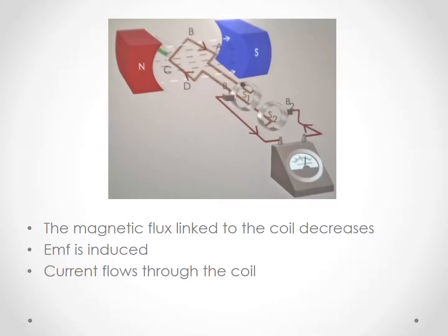Now, as we continue to rotate our generator in the clockwise direction, we notice that there are 4 lines passing through the coil and 2 lines not in the coil. Now, since there is a change in magnetic flux, there is EMF induced in the generator. But notice something different here. The direction of the current induced in the generator is in the opposite direction.